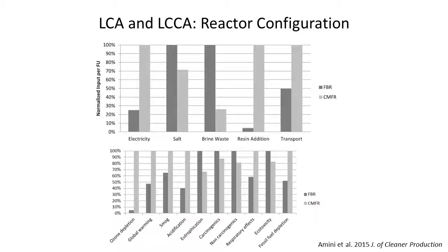And then one of Jane's students, Adib, went in Florida and collected full-scale data for several ion exchange plants. So we have some ion exchange plants in Florida that are a fixed bed configuration, and we have a handful that are completely mixed configuration. He collected all what's referred to as the inventory data in terms of all the material flows into the system, the material flows out of the system, the energy, in terms of doing the life cycle assessment. And so here what he's trying to do is compare electricity use, salt use, brine waste, resin addition, and transport.